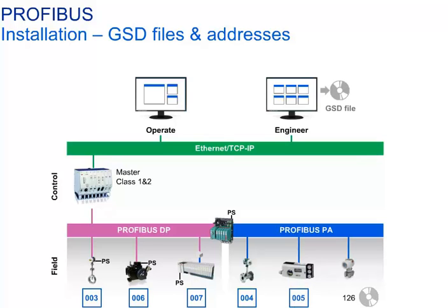It's important not to run two field devices with the same bus address simultaneously on the same Profibus line. Profibus field devices have no fixed position on the bus. This means the bus addresses may appear in any order.